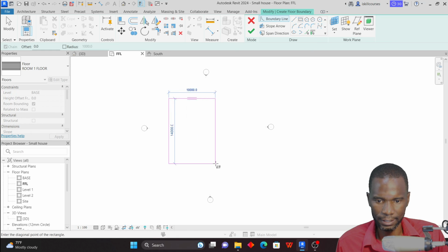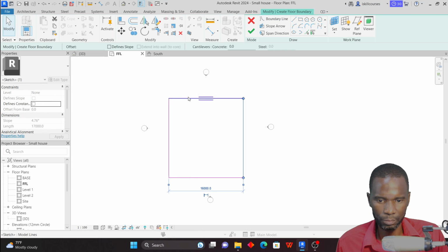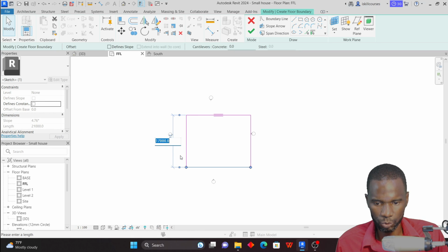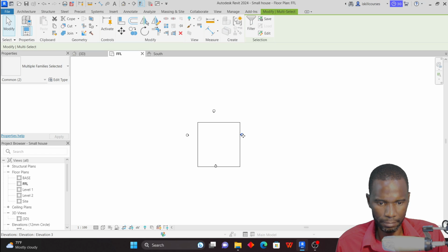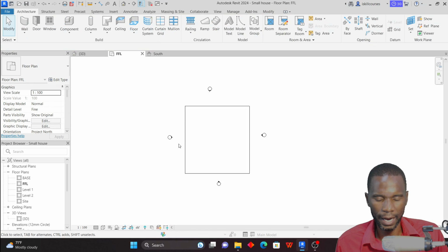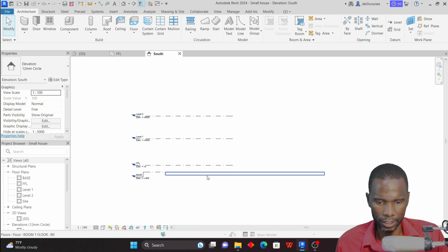First of all, I'll click the first point and the second point, and now I can specify the dimensions. Maybe the horizontal one, I just want to have 21 meters, 21M on your keyboard, enter. I'm happy. Then maybe the vertical one, I just want to have 22. I can select this one and type 22M and enter on my keyboard. Then click on finish. Then you see that I have these elevation markers. I can move it here and select that one and move it somewhere there. That is how you can move these elevation markers. So I have the base, and we have created this at the base, as you can see from here.